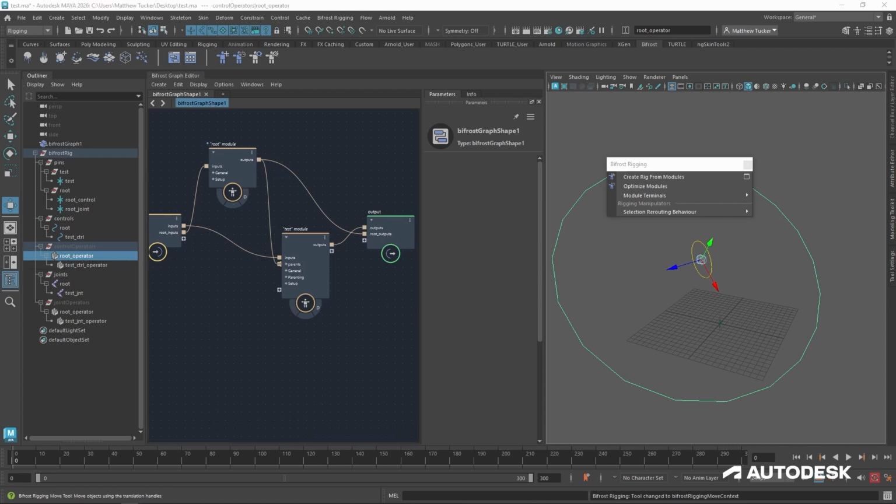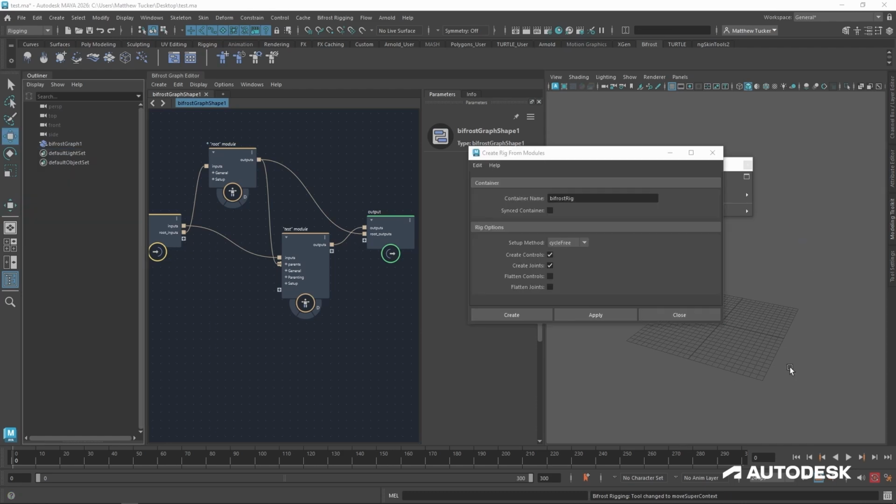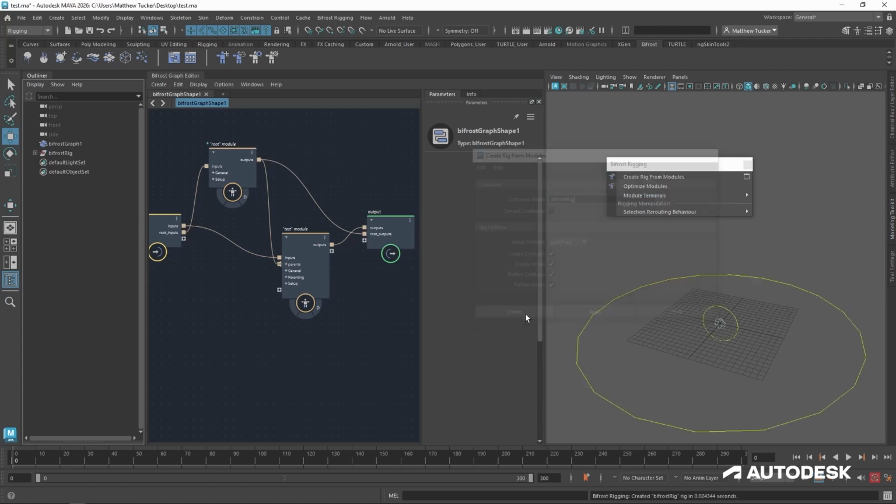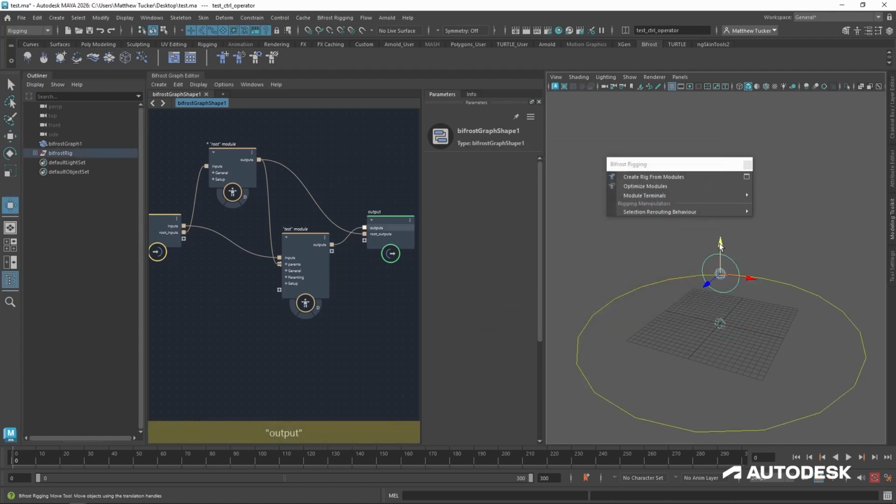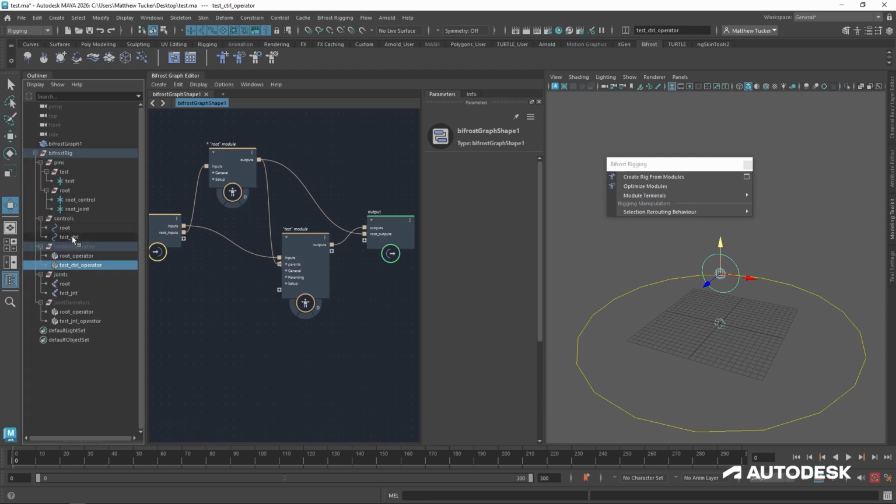Now the advantage of the cycle-free mode is that it's faster because it eliminates scene evaluation overhead from Maya. Now one final thing of note in the rig options, if I flatten the controls and flatten the joints and create a new graph, we can see the joints and controls are no longer direct parents of each other, which is great for speed, but unfortunately it will make exporting your skeleton a little bit more difficult, and you can no longer pick walk your joints or controls.